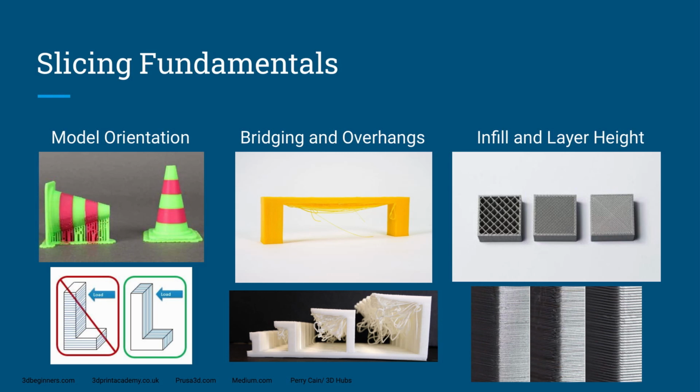Also, there is something called infill, which I touched on a little bit before, and that is the density of material in your 3D models. On the leftmost block, it is pretty open with that grid, and then the middle block a little bit more dense, and the block all the way on the right is 100% infill. So normally when 3D printing, you don't need your part to be solid, right? So you can do 15% infill, 20%, and that'd be plenty strong for most applications.